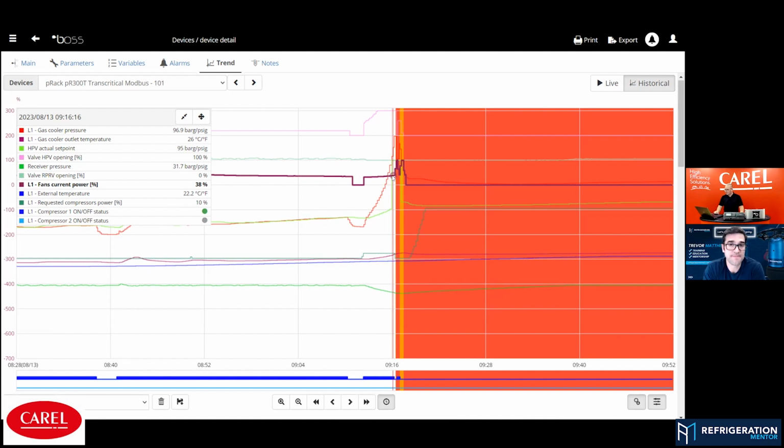Exactly. So the fans don't ramp up. What could it be? If you take a look really on this graph, there's only one point that could be this issue, our high pressure valve. It's the only thing that could really make this kind of problem without producing other problems. So our blocking part is between our compressor and the high pressure valve. Would it be after the high pressure valve? We would see it directly in our receiver pressure valve. This would open.